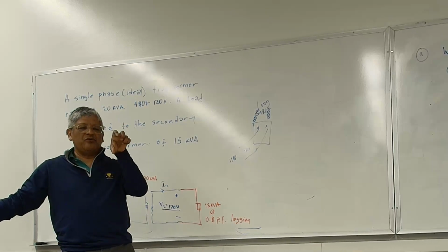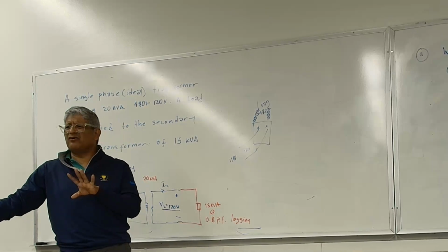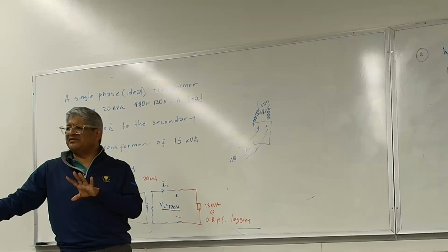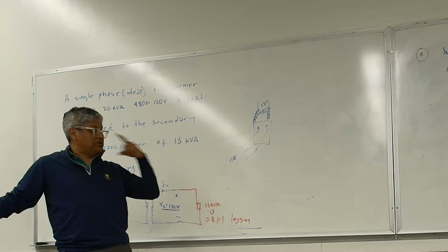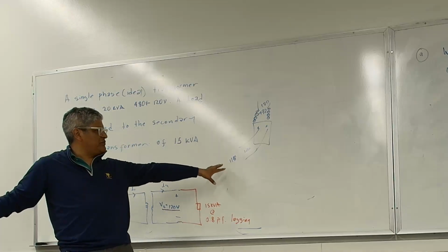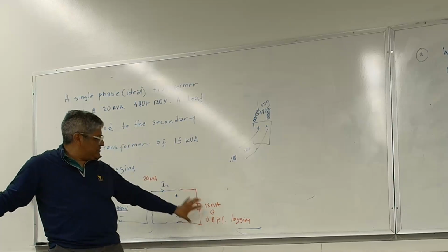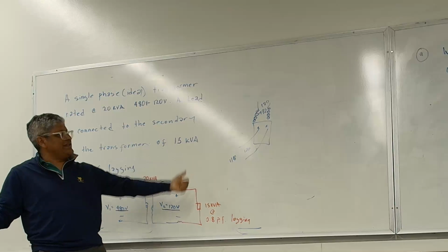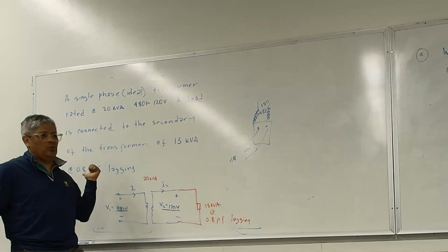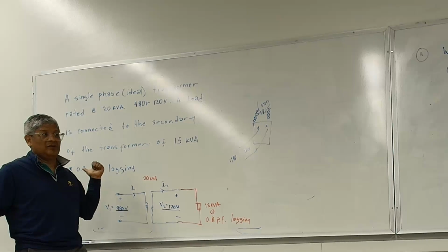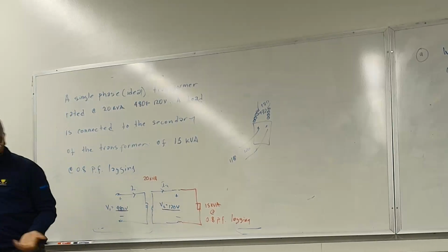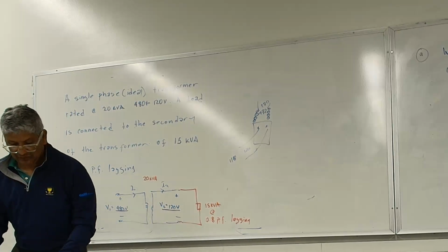Towards the end, I'm going to cover per units. Have I covered per unit with you guys, right? The per unit system? Okay. We'll talk about how to normalize these voltages. But for now, what all this problem is saying is, I know whatever is connected is dragging the voltage down to 118. I want to know on the primary side, what is the voltage the utility is seeing right now? Okay? That's basically what the question is.